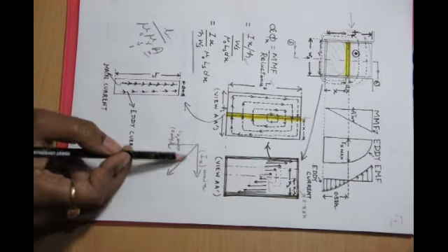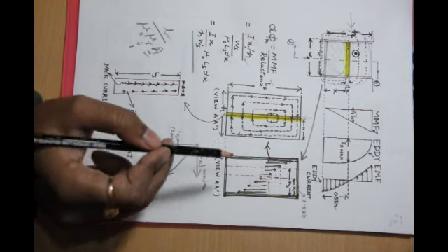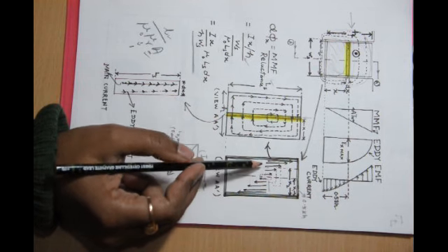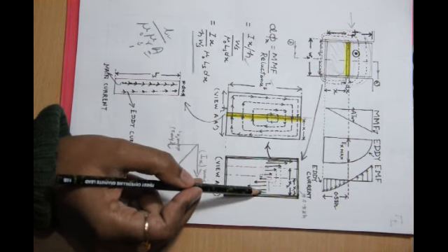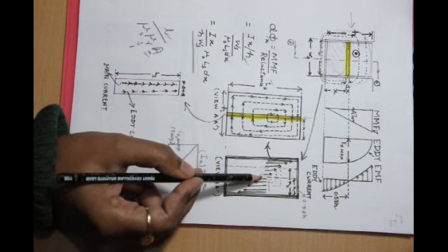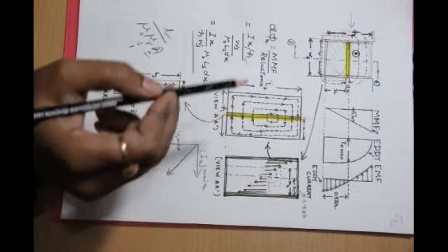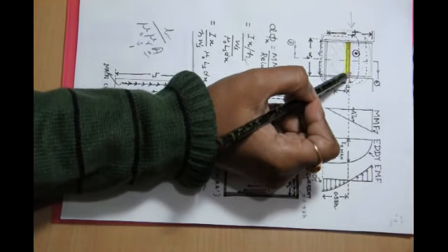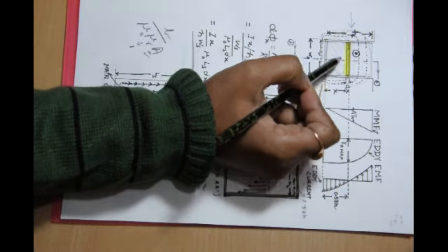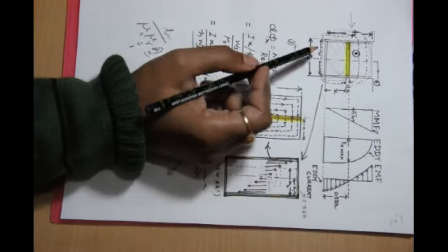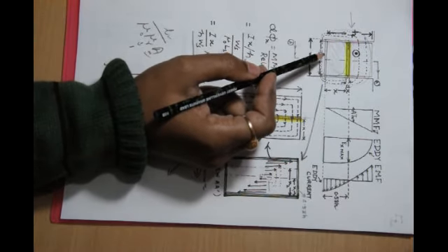And when you add them vectorially, we'll find that the total distribution of current is more in the outer areas and lesser in the inner regions. In other words, the total current would be distributed larger in the outer areas and lesser in the inner areas. This phenomenon is known as skin effect, and this increases with increased frequency.